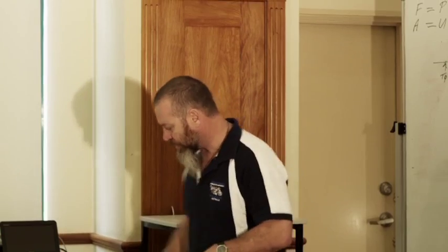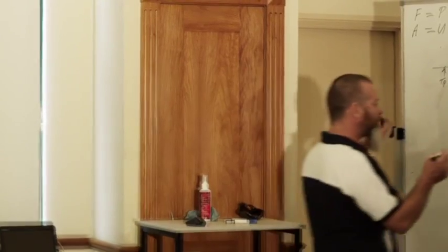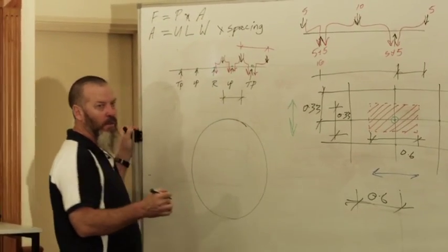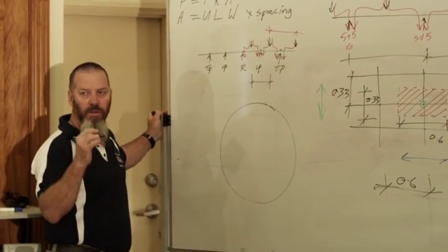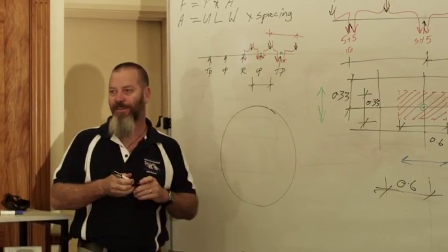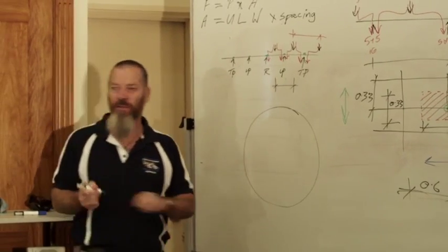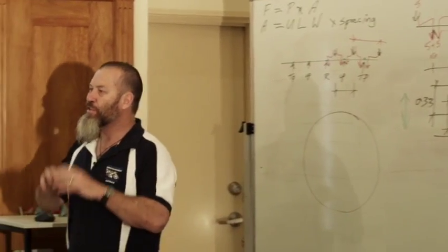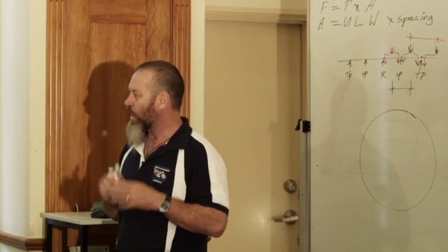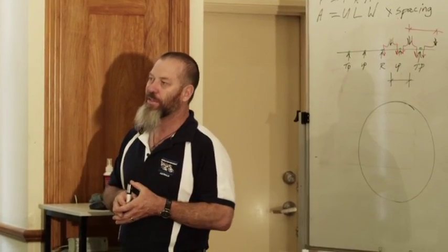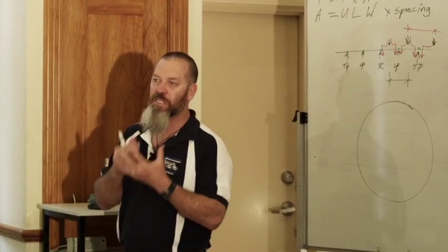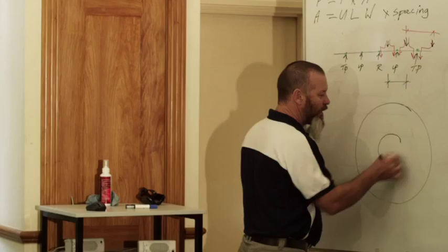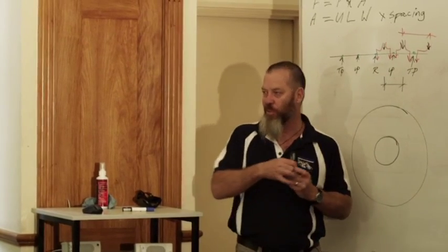Now the heart, just by way of explanation, I'll tell you a little bit about trees. When you're treated hardwood is kind of a bit of a misnomer, because you can only treat the sapwood of a piece of timber. You can't treat the heartwood. Even in pine, it won't accept the treatment or it won't hold the treatment. Now a pine tree has a heart about that big proportionately.